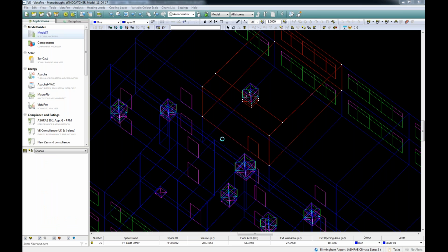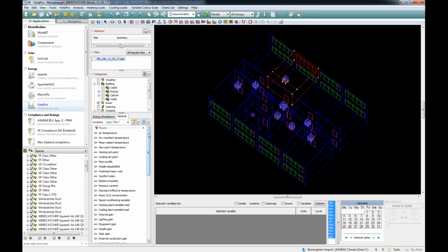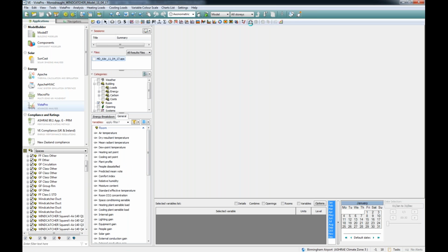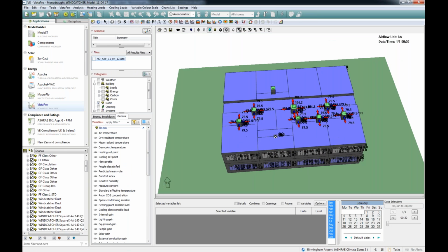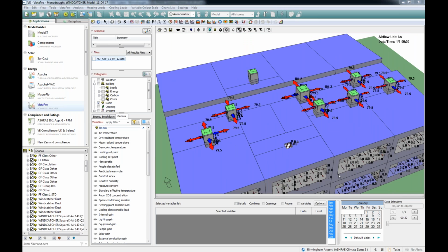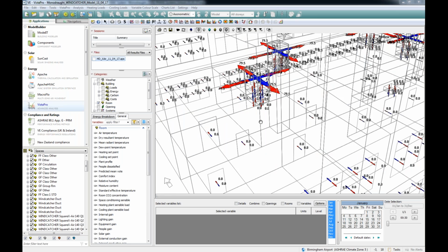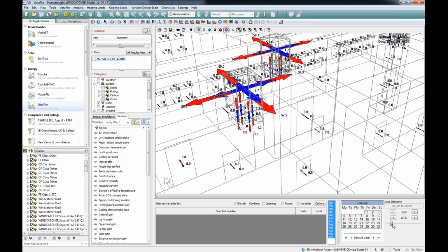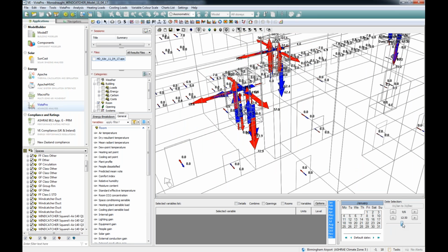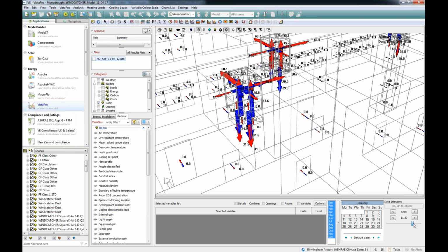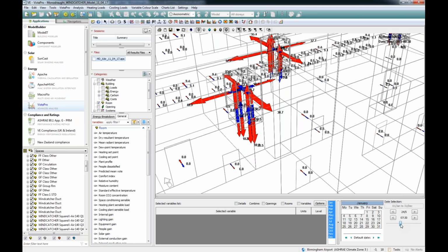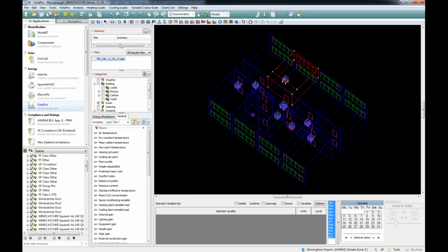Just quickly for the results, in terms of checking the ventilation going through, one thing you can do is go to the Vista Pro, go to the macroflow opening arrows, and then on the particular model, if you go to the wireframe view, it's a little bit busy, but you can view the systems and the change in ventilation rates going through each quadrant of the Wind Cat system, so you can check that it's operating.